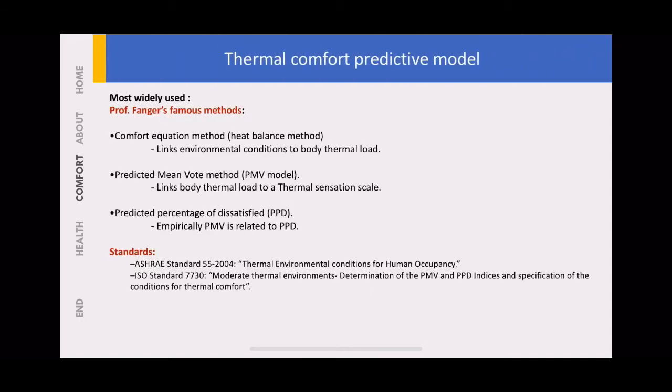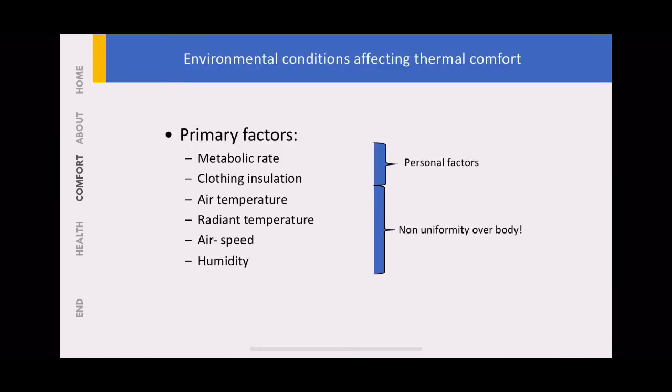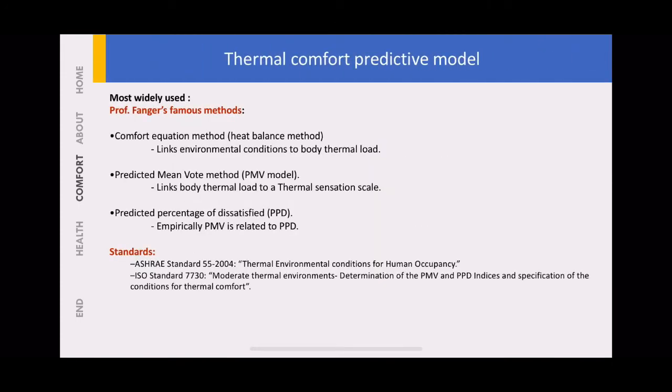Right, thermal comfort. Oh, where did it go? Alright, the thermal comfort predictive model is designed by ASHRAE, or the pioneer would be Professor Fanger, and his famous methods were the comfort equation method, which is the heat balance method, linking environmental conditions to body thermal load. These talk about the calculations that we have done.